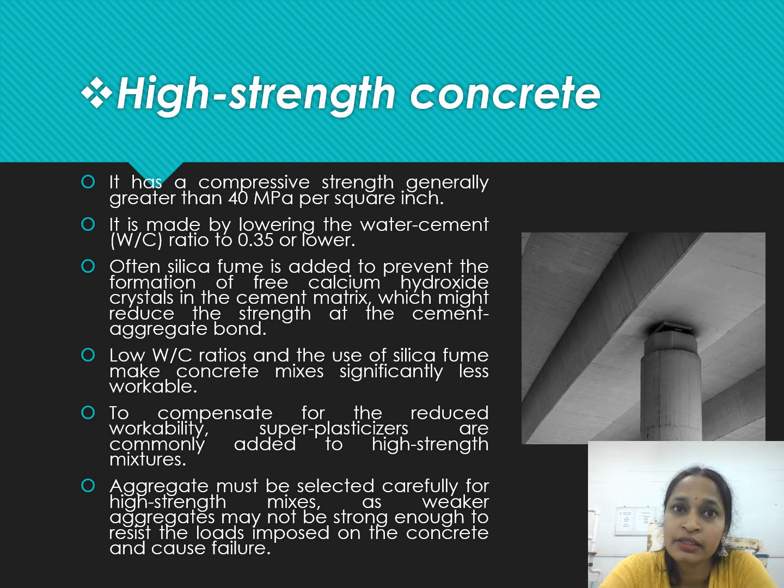So what do you say? Is it giving good performance? I don't think so. The initial strength is high, but later its performance is not good. So high strength concrete has to concentrate on all these factors like long term durability, everything. Basically, the compressive strength generally is greater than 40 MPa. It is made by lowering the water cement ratio to 0.35 or lower.